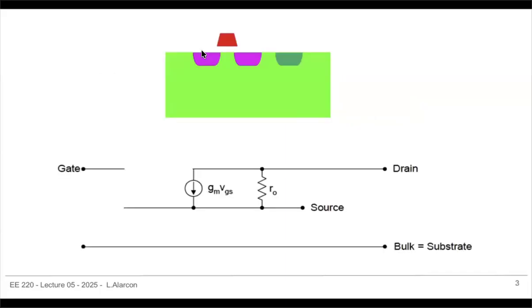So let us take a typical NMOS. If this is a typical NMOS device, then we have a P substrate, and your N regions, and in general you have your P tap. This is going to be N plus. This is your gate, and potentially your source and drain.